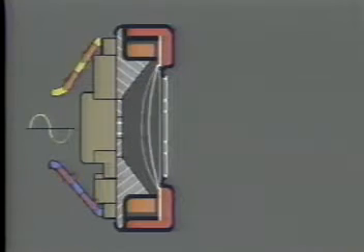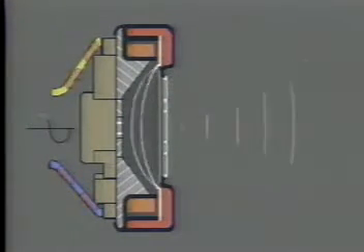Again, electrical signals enter the receiver by flowing through the wire of the electromagnet. As the electrical current increases and decreases, the electromagnet alternately aids and opposes the permanent magnet, driving the entire structure like a piston. When the diaphragm vibrates, the nearby air molecules are compressed and relaxed. It's this vibrating air which actually recreates the sound waves which were originally directed into the transmitter.